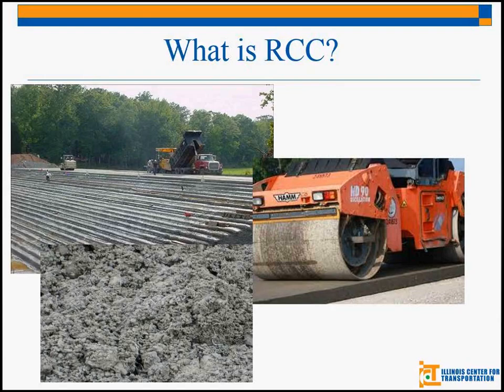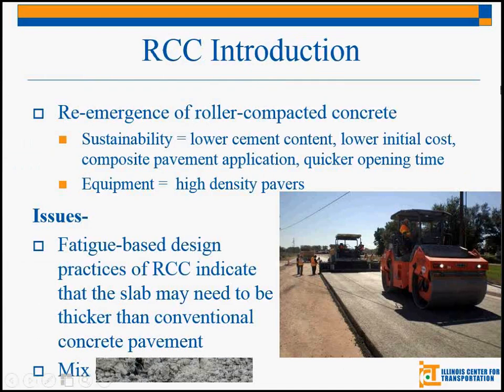Okay, so what is RCC? RCC is roller compacted concrete. Roller compacted concrete is basically what it sounds like. We have concrete, and we use a roller to obtain density and make it dense. The reason we do this is because it's typically a drier mix, as you can see down here. It looks a lot more like dirt that's really, really dry. It has a low cement content and typically a low water to cement ratio, so it is very dry, and we use the roller to achieve density. That way we can use aggregate interlock to help increase our strength.